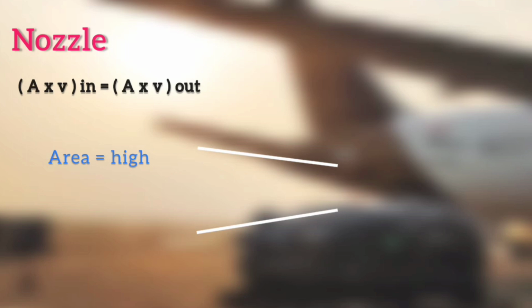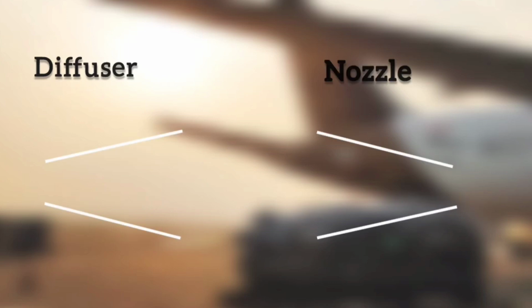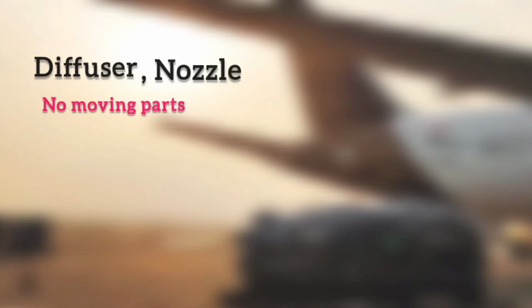Similarly, we have the nozzle, where the area of the inlet is more and the area of the outlet is less. From the mass flow rate equation, we can say that the velocity at the inlet is low and the velocity at the outlet is high. Therefore, from Bernoulli's theorem, where pressure is inversely proportional to velocity, we can say that the pressure at the inlet is higher and the pressure at the outlet is lower. The diffuser and nozzle are simple components with no moving parts. They can be used to change the velocity and flow at different sections of the engine to alter the pressure.